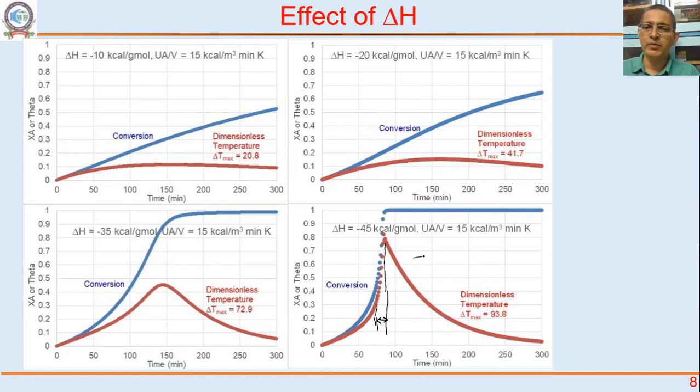This is what leads to our runaway behavior, because at this high temperature, some other reactions can happen, solvents can degrade, decomposition, some auto ignition temperature may be reached, suddenly it goes up and then you have all kinds of problems, you have explosions happening and so on and so forth.